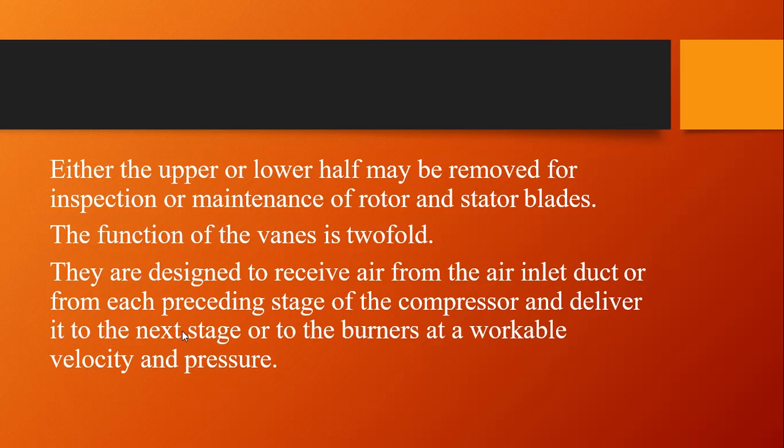The function of the vanes or the blades. One is to receive air from the air inlet duct or from each preceding stage of the compressor and deliver it to the next stage or to the burners at a workable velocity and pressure. That's the role of the vanes or the blades. They receive air from the duct or from the preceding stage of the compressor, and they deliver it to the next stage, or at the end of the compressor they give it to the burners at a workable velocity and pressure.